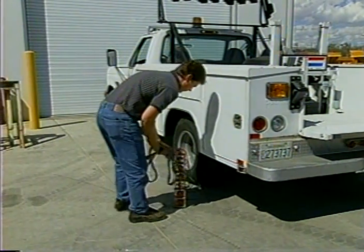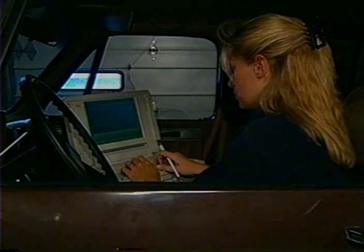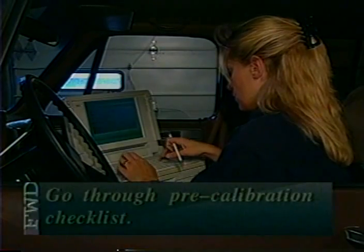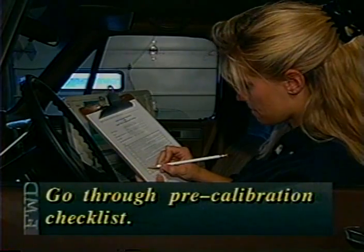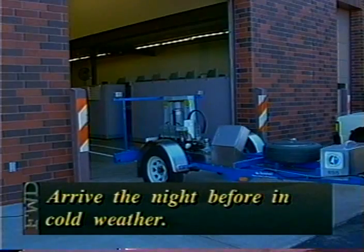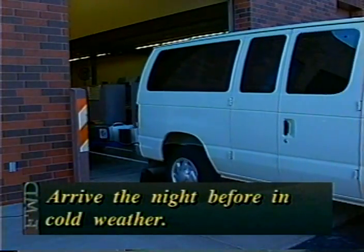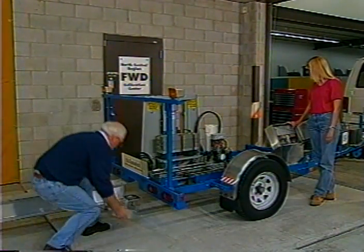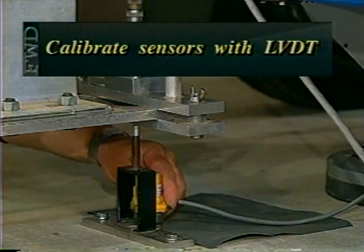But we've gone through a lot of information here, so let's quickly review the calibration process. First, you prepare before you leave for the calibration center by going through the pre-calibration checklist. If it's cold outside, plan to arrive at the calibration center the night before so your FWD can stabilize at the temperature inside the calibration center garage. When you begin calibration in the morning, the first thing is to compare your load cell with a reference load cell. Then you compare each sensor with the LVDT.